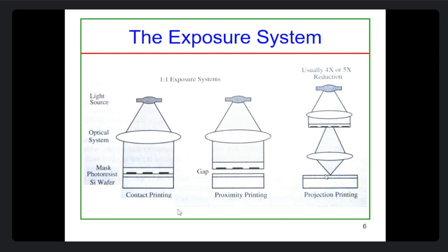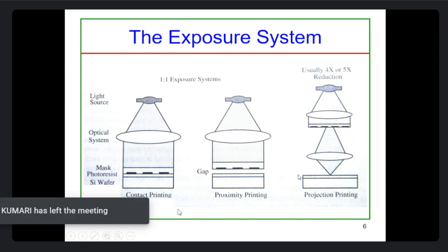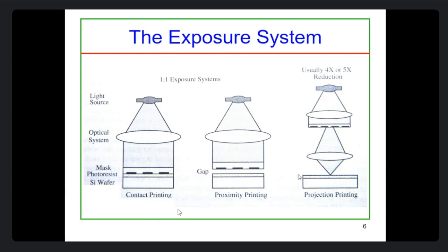Okay, so it is kind of step and repeat. You see, the step is basically getting repeated. So the entire wafer is not printed or written at the same time. It goes die by die, one die at a time, then another die, and so on. That is basically it. It's a cross-sectional view. In 3D, it's a circular disc, and you go for the step and repeat.